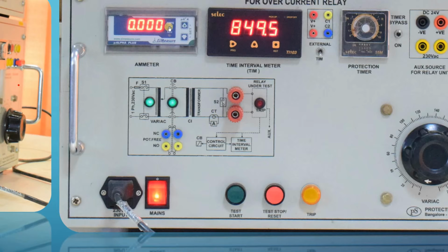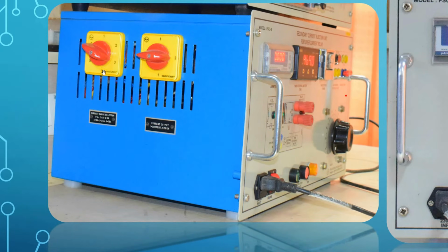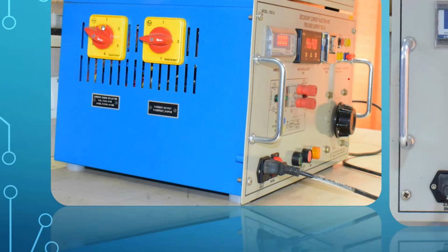So the full scale reading of this ammeter is 1 ampere. That's why it is connected through a CT, which adjusts the ratio. Whatever current is fed, it is converted into a 1 ampere scale, and the original current flows according to the CT ratio. Where the CT ratio is adjusted, as you can see on the left, is the current range selection switch. At position 1 it is 1 ampere, position 2 is 2 ampere, position 3 is 5 ampere, position 4 is 10 ampere, like that.